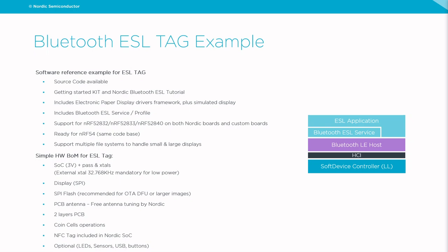When it comes to hardware, Nordic provides all that is needed to create a tag. Using the Nordic SoC, it's easy to combine the Nordic reference design with third-party display reference designs to build your custom board. The high level of integration of the Nordic SoC means reduced bill of material and lower cost for the entire product. As we have seen in one of the previous demos, a tag can be built from as little as a Nordic nRF52840 dongle.